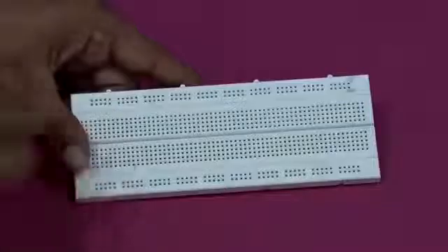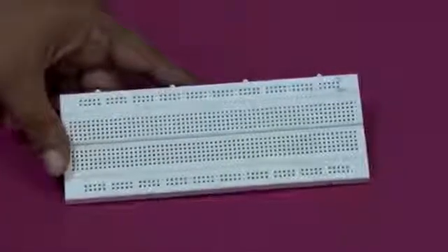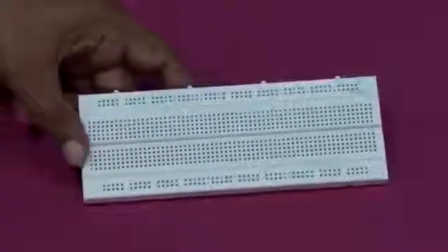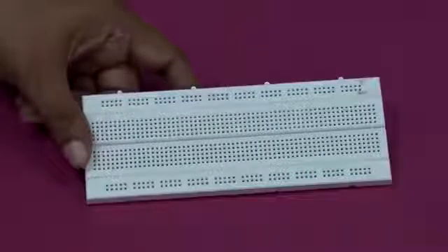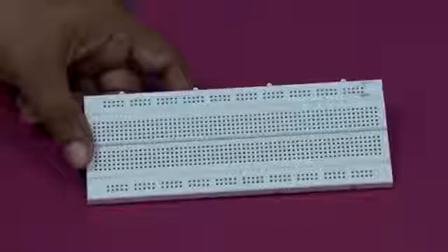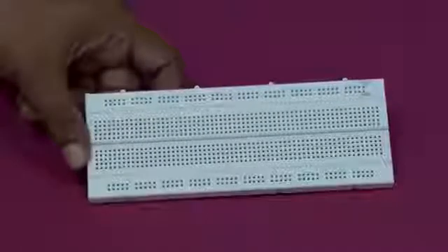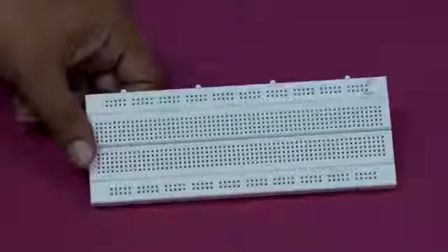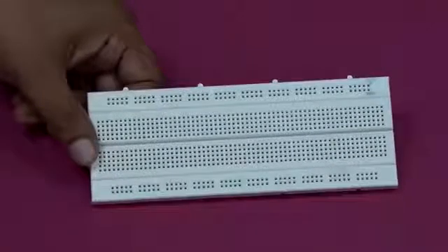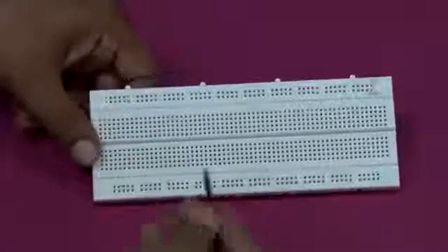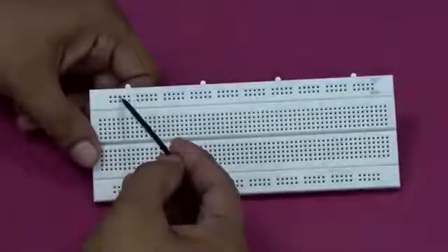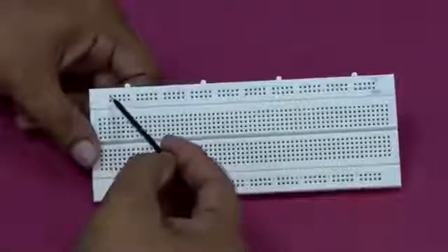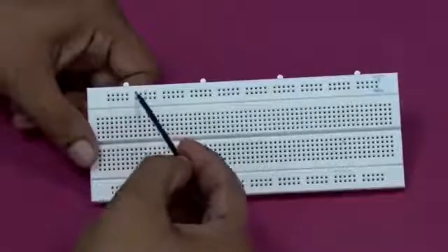So, now Ranjit has to help me. As I said, you have all the negatives of the battery, the black terminals of the multimeters, the emitter, they are all connected to the zero potential line. They have to be connected to each other, which we will be calling zero potential. So, on this breadboard, I will be using this line here for that zero potential. They are all connected to each other.